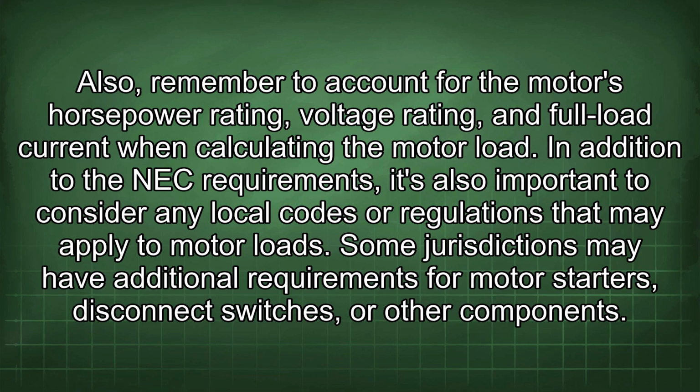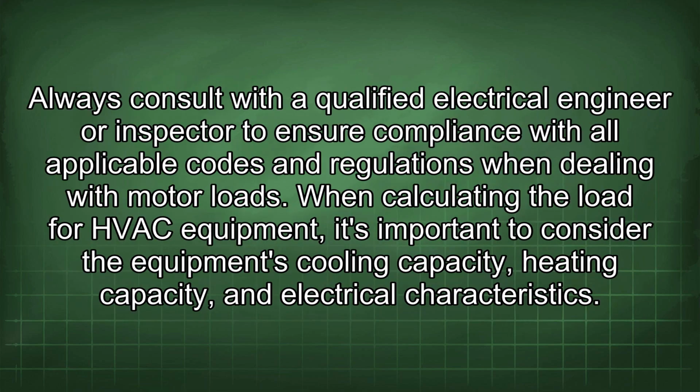In addition to the NEC requirements, it's also important to consider any local codes or regulations that may apply to motor loads. Some jurisdictions may have additional requirements for motor starters, disconnect switches, or other components. Always consult with a qualified electrical engineer or inspector to ensure compliance with all applicable codes and regulations when dealing with motor loads. When calculating the load for HVAC equipment, it's important to consider the equipment's cooling capacity, heating capacity,